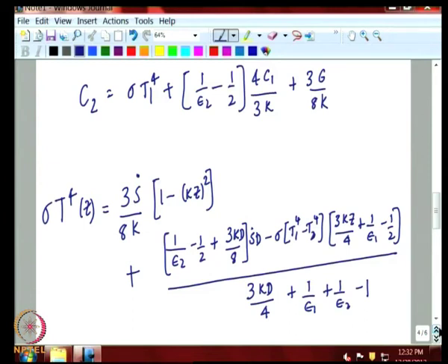First, let us again take the case of black walls, in which this becomes 1 plus 3 k d by 4, and this will introduce a half here, and here you will see that now we have to see the relative importance of the heat generation versus the wall induced heat transfer in the medium. And you can see clearly that now there is a new parameter coming in, the heat generation into D by sigma.